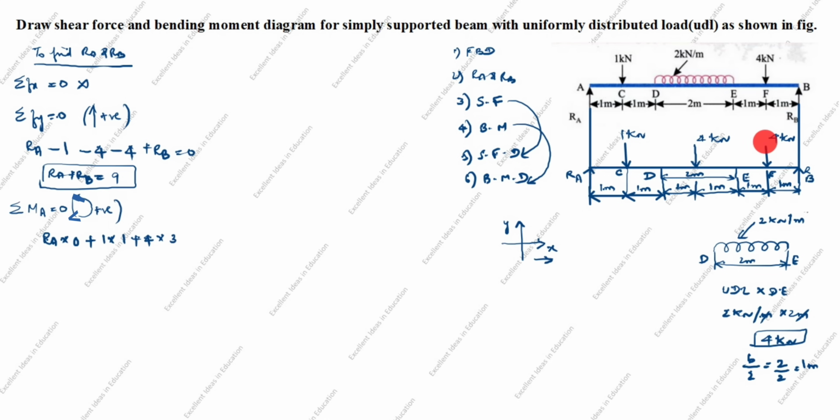Next, we will see this force. This force also clockwise. You see the arrow comes down. Plus 4. What is the perpendicular distance in this? From here to here we will calculate. So what is the distance? Distance is 5. Next we will take this force. You see the arrow goes up. Up is, you see, from here to here, it's anti-clockwise. Anti-clockwise is negative. Minus RB into, what is the perpendicular distance from here to here? You can take 6 equal to 0.